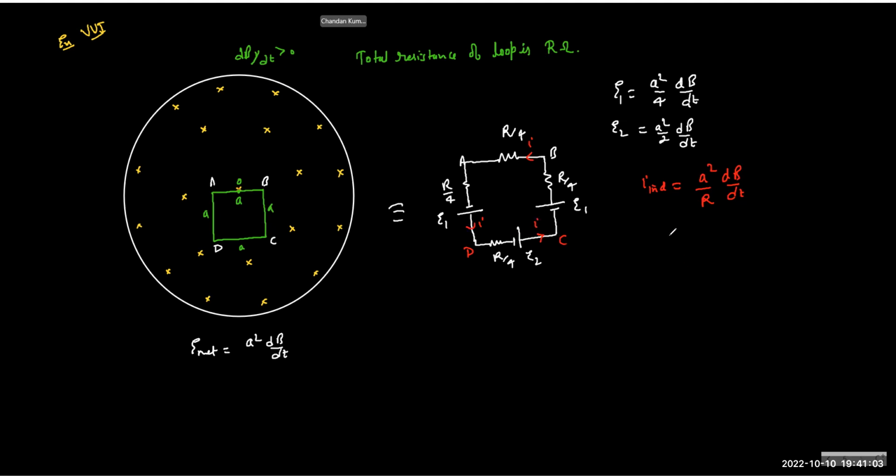So what is the potential difference between A and B? You can see when you have a current, then in the direction of current, potential will decrease. So now you can write VB at high potential. So VB minus VA will be IR by 4, correct? Yes. And IR is basically the E net. It is E net by 4.